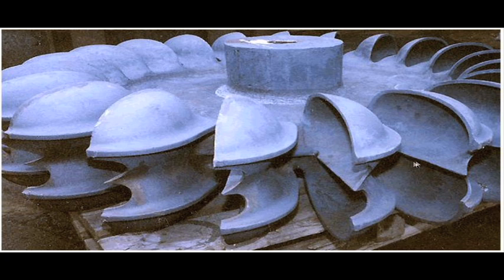So, the water jet strikes here and flows along the buckets in both directions. These are the spoon-shaped buckets as I have shown you in the other picture, and here it is very clear. If you see the fluid inlet and the outlet in both the halves, both inlet and outlet take place at the same radial locations, and the flow direction is mainly tangential.